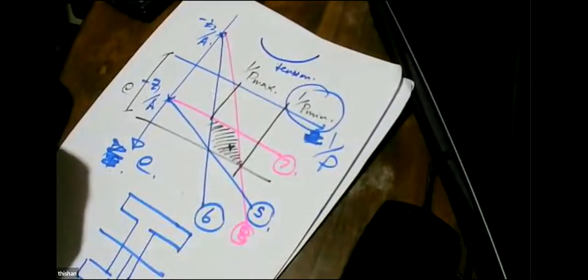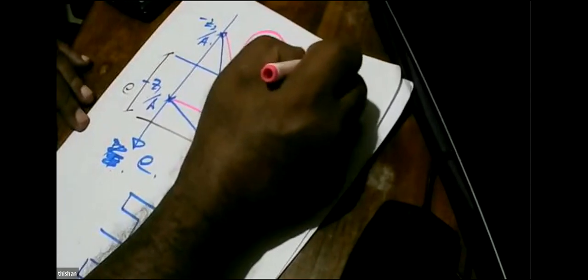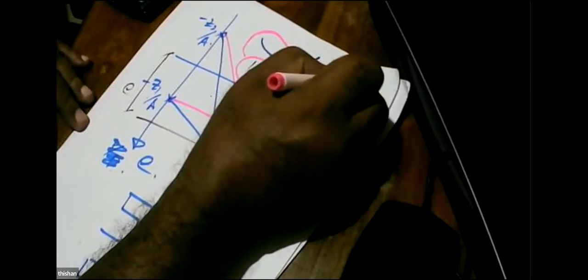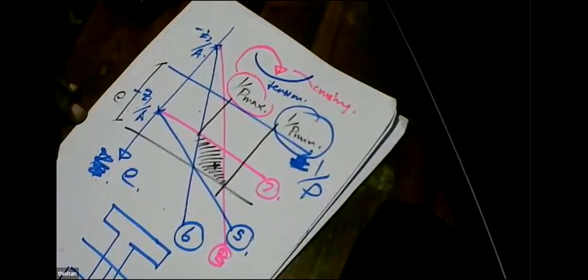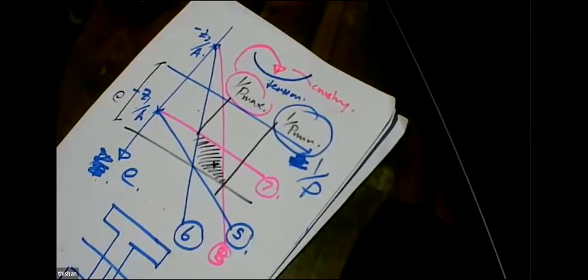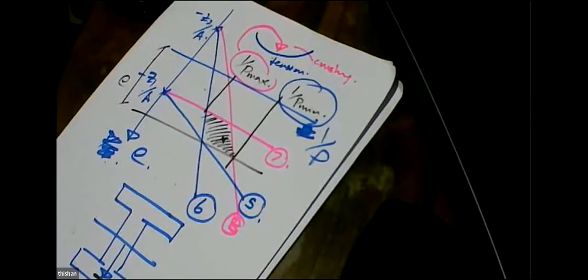When you use this maximum, how can it fail? It will fail at the top fiber with crushing. Which one is better? Crushing of concrete or yielding of reinforcement? Cracking in tension or crushing in concrete? Which is better? Always a tensile crack in concrete is better because it gives us the warning, right?